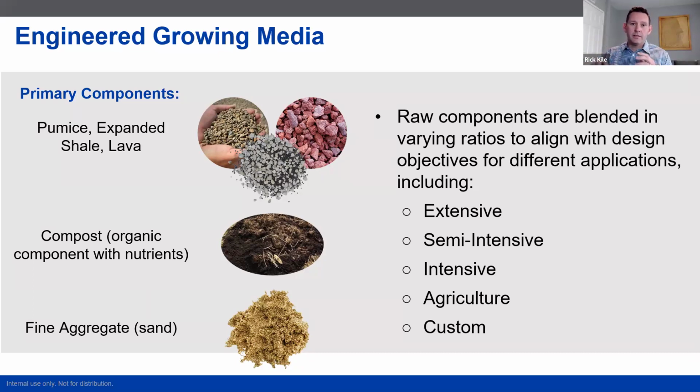When we look at vegetated roofing, I don't like to look at it as a finite product. We really have the ability to tailor these assemblies to the project. It depends on where the project is, what they're looking to plant, what's the project objective, what's the programming, and then how do we tailor that assembly to the project to fit within those thresholds. So we'll give some ranges as we go through extensive, intensive, semi-intensive.